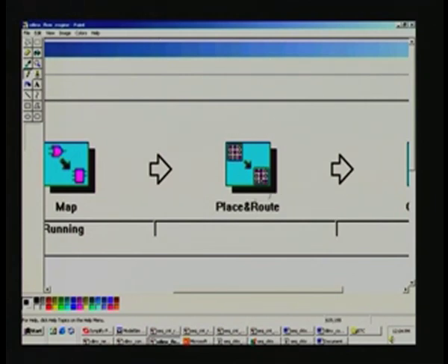All these inputs are provided, mind you, by the .edf file which we have already seen, and based on those inputs it will start routing from one pin to another if it is an external pin, and in fact to the inner pins for the functional modules. Primitive cells also have their own IOs, not actually pins, but the functionality within. All those things will be taken care of, and it will do the total routing here.